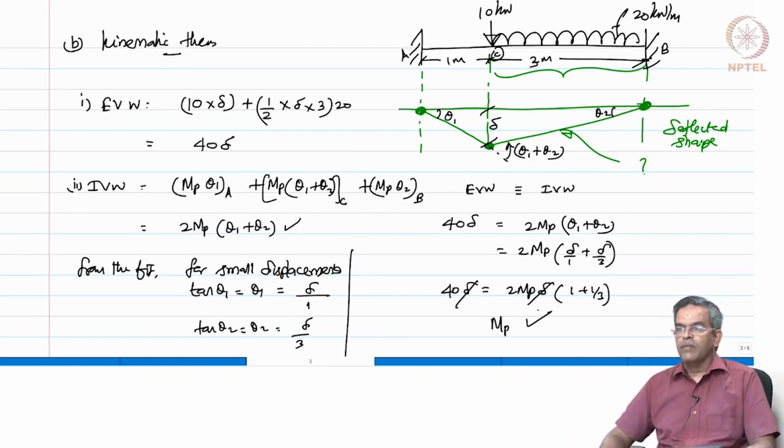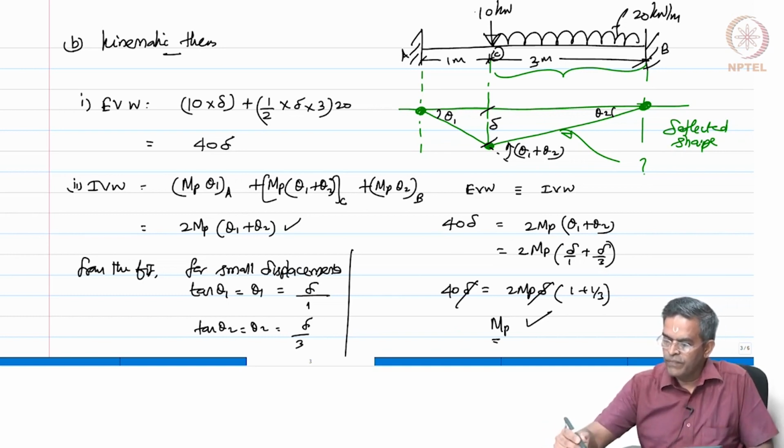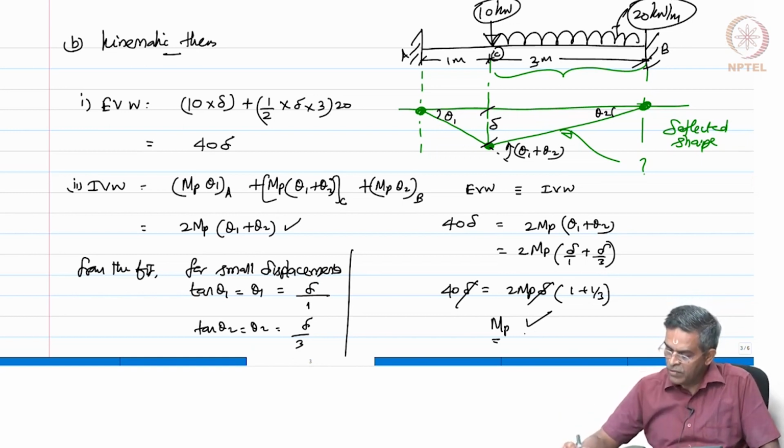It is a straightforward problem, right. So, this matches with the assumptions we made in the number of plastic hinges formation, and I am able to get my MP. Where I consider this load will be the subjected load on the system. So, obtaining MP for the analysis is plastic design.